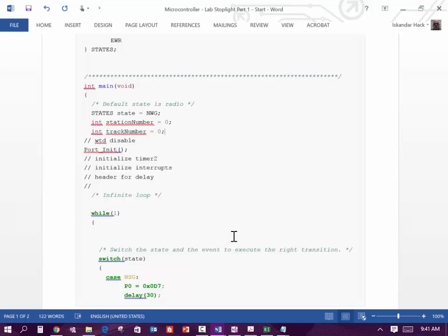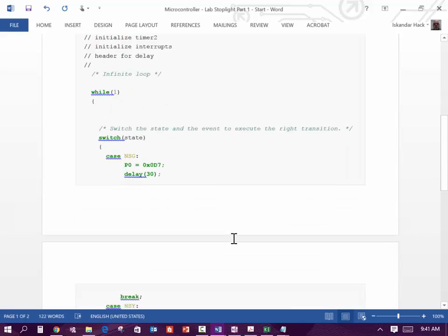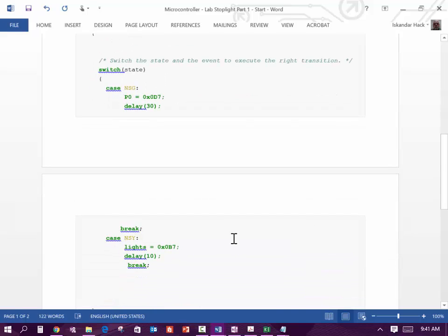The only thing is at the end, actually you don't change anything, because main you're replacing with this finite state machine. The only thing that was in main, as you recall, was you just simply called delay and then toggled the LED. Here you replace main with this state switch machine.